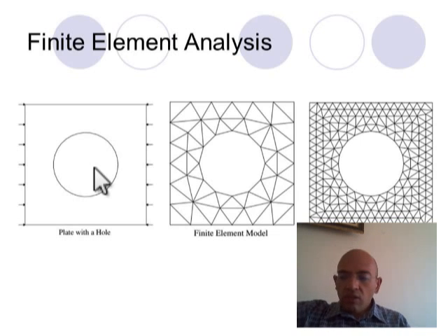Perhaps you remember the truss systems. What we do is we write the force equilibrium for each junction. Then we have a set of linear equations, and we solve that set of linear equations in order to find the forces acting on each truss element.